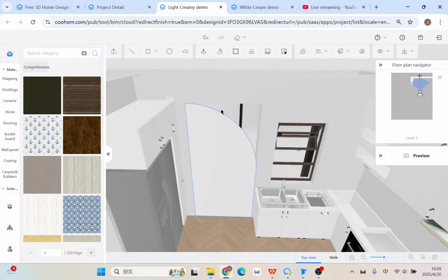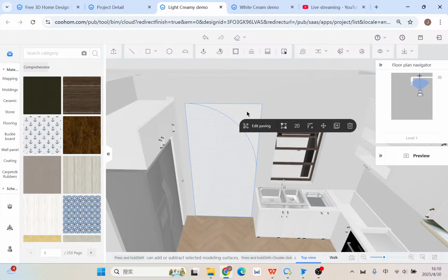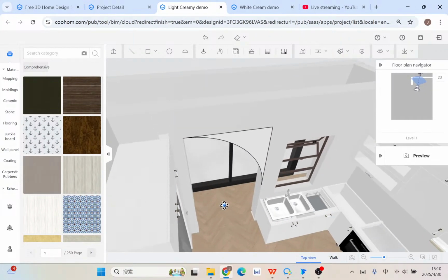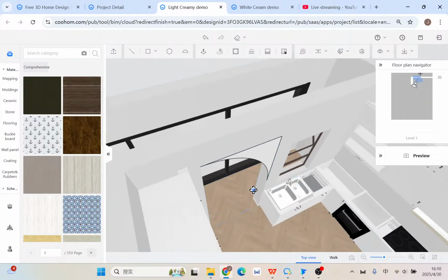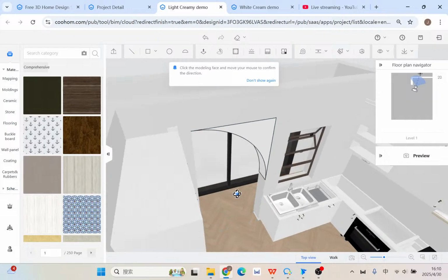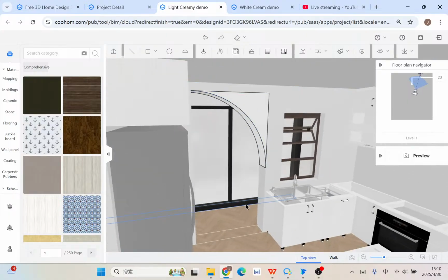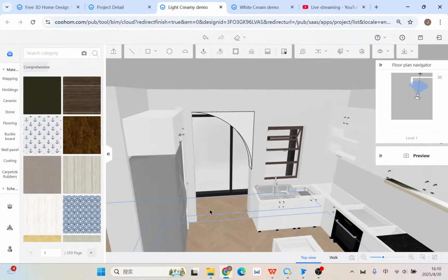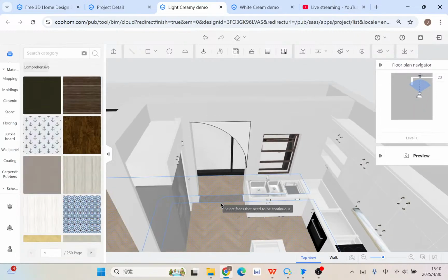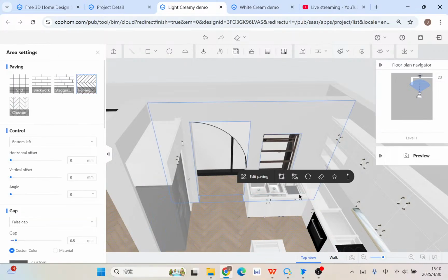Okay. And then this is not the end. You go another with the rectangle and draw them back, because I just need to use the corner. I don't need the entire shape, I just need the corners. Then what I need to do is use push and pull to give certain depths. Type in numbers and then end with enter. So you can do it. Finally, don't forget to check the connect faces. Yeah, because here I already did that.